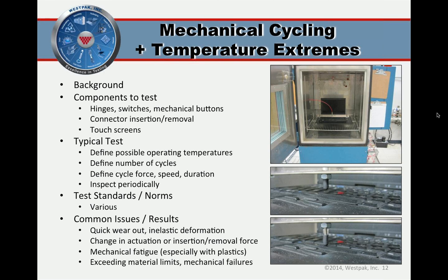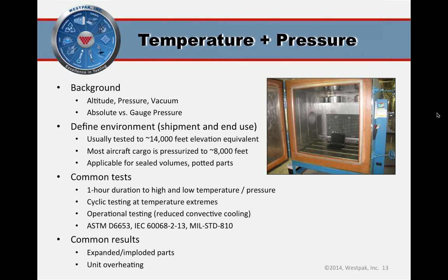So at times, this effect has been known to decrease the intended damping of a rotating member, for example, resulting in product damage. Sometimes we've actually seen hinges get to be tight at higher temperatures, and sometimes hinges that were designed to hold at a certain position with internal damping would, at low temperatures, because of the contraction of the material, actually fall out. So make sure you test all these mechanical devices at temperature extremes. Back to you, Mike. Thank you, Herb.